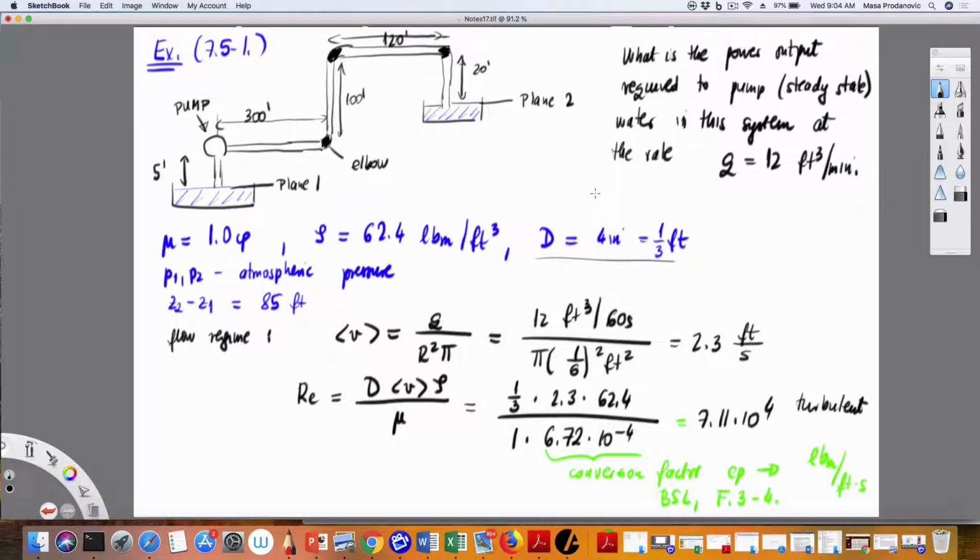Now, what we have to treat separately, we did come up with the energy balance, or macroscopic energy balance formula, last time around. So we do have the formula, and what we need to do is break this up. There are friction factors in different types of geometries, and we know that these things are sensitive to the type of geometry I'm flowing through. One of them is the familiar one, that is the tube. The other one is not necessarily familiar, or we haven't worked with it. Those are the elbows, or these 90-degree turns. But there are tabulated values that one actually resorts to. It's not perfect, but it's an estimate.